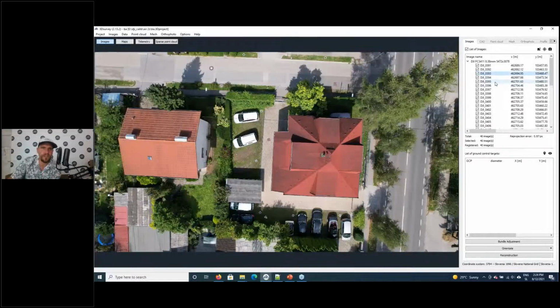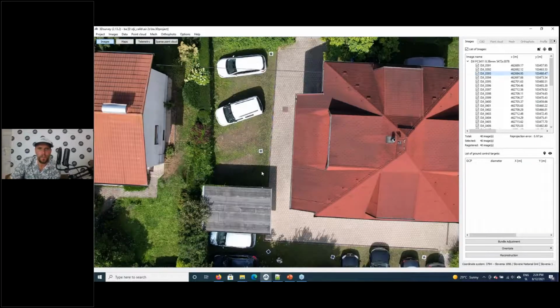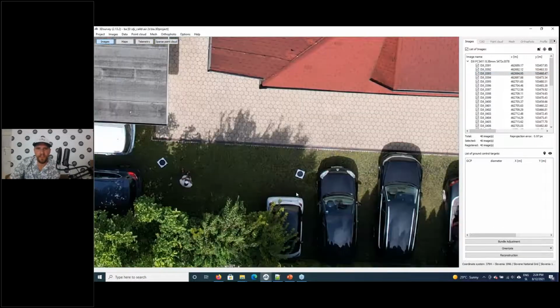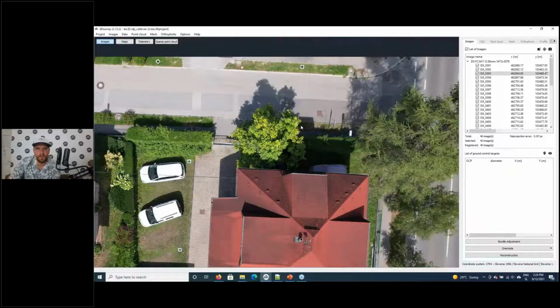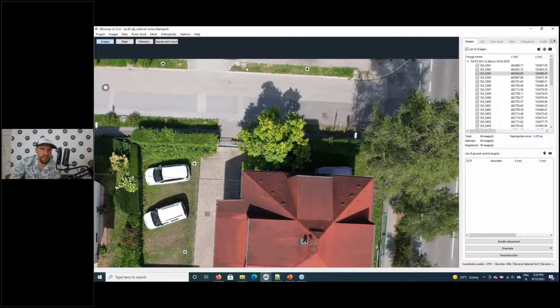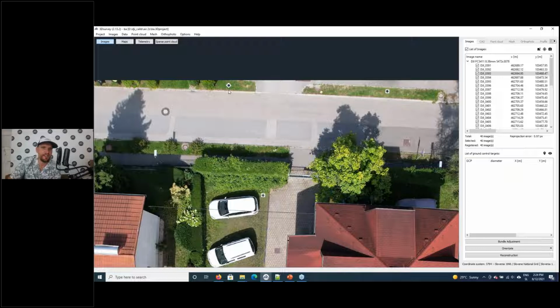So here on this small area, I signalized 9 ground control points and placed them in a grid. Because we have that many of them, this will allow us to calculate our focal length very accurately. It's just important that these points are measured accurately, that they are stabilized and they don't move during our measurements. So these are general instructions. Now let's do the orientation with GCP data.